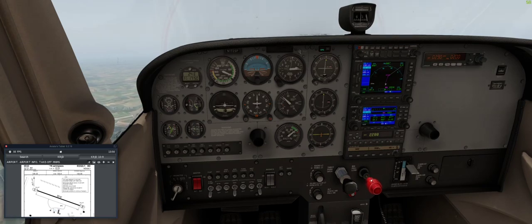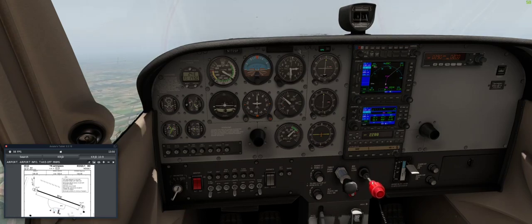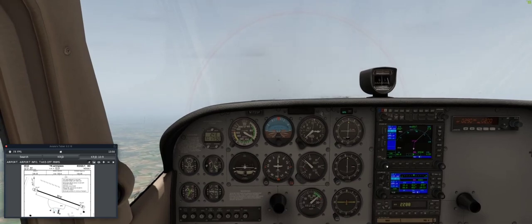Not only is fuel efficiency bad, but it is not the greatest thing in the world for your engine to run that rich either. I'm going to pull this out until the EGT maximizes. And look at fuel flow dropping. Our power and our RPMs aren't dropping. Up, and you see the EGT started up as I continue to pull. I reach that point and the EGT starts to drop again, so I want to back it up and leave it about right there. We're at 2,500. I'll do that again when we get to the cruise altitude.